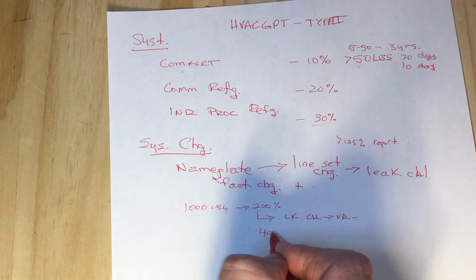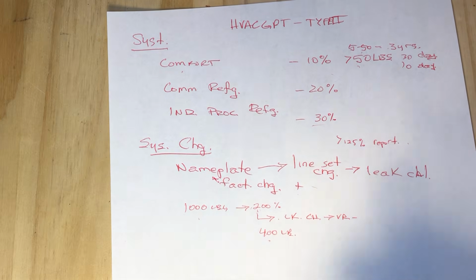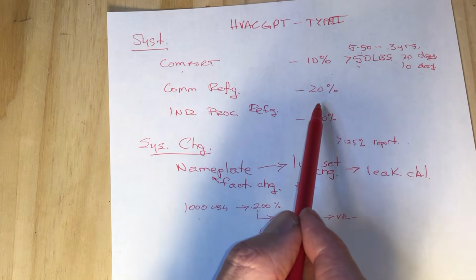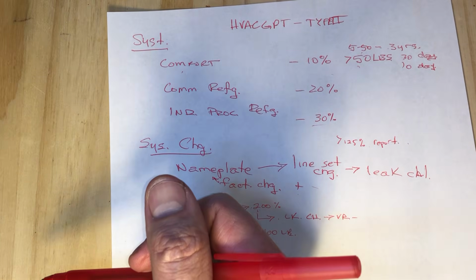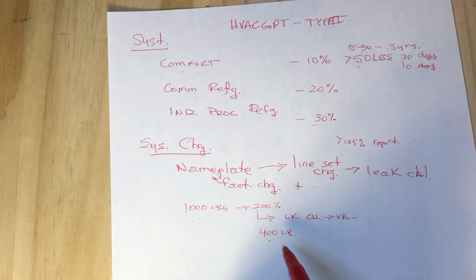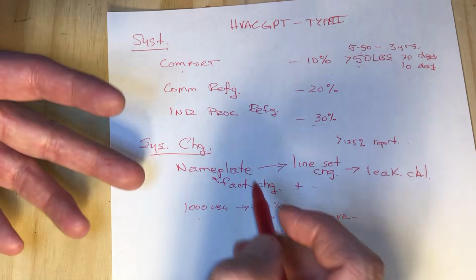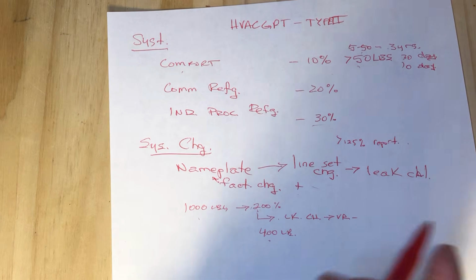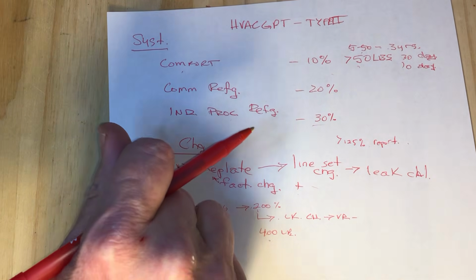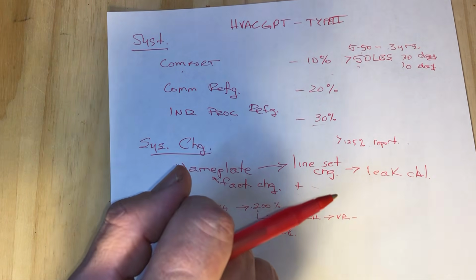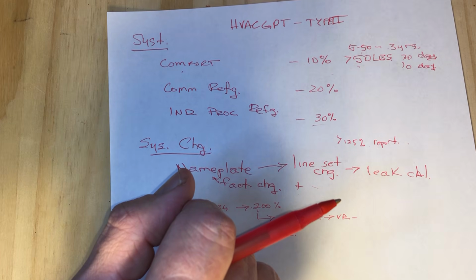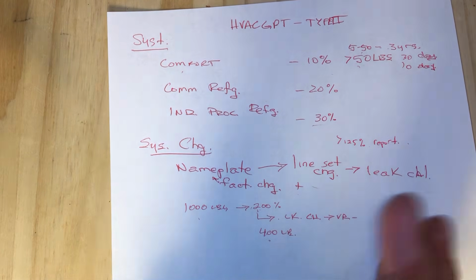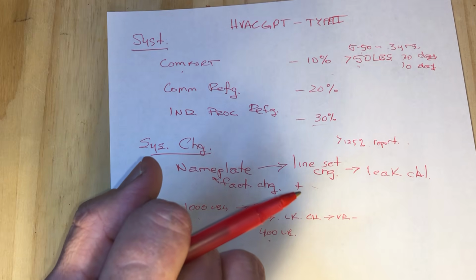The other thing you probably should know is that if you have a unit with, let's say, maybe 400 pounds of refrigerant leaking out of it, that's 40%, and it's industrial process or any of these others, you are going to maybe think about replacing the unit. They have this thing in the test they call mothballing the unit. Let's say you have a backup unit, then you can do this thing called mothballing, but you've got to isolate the section of the unit that has the leak and remove any refrigerant, and that's one of the requirements. And then you can stop the clock. That's one of the requirements, to stop the clock if you want to extend time on that repair.